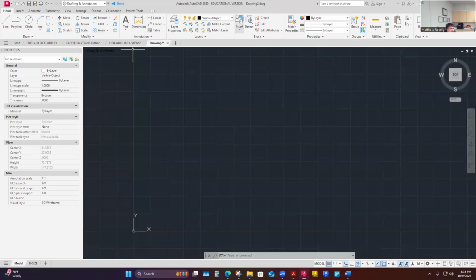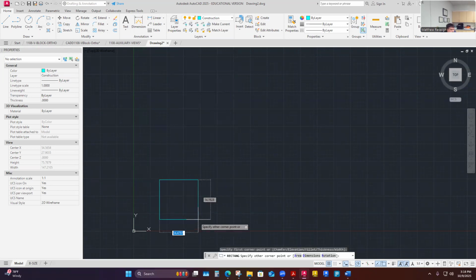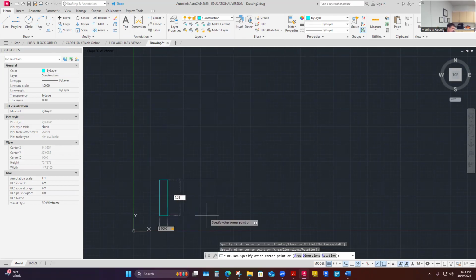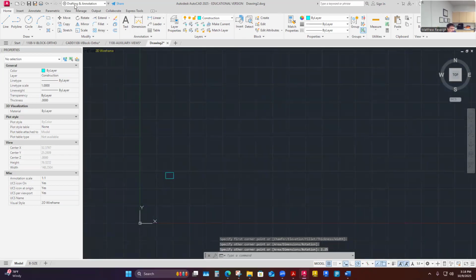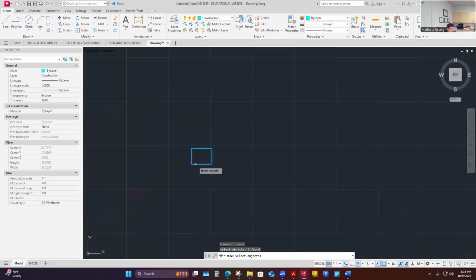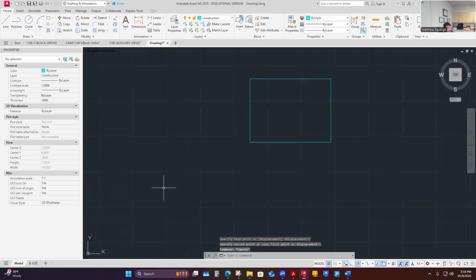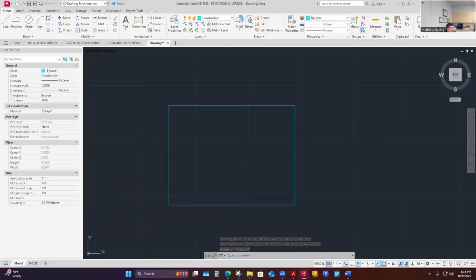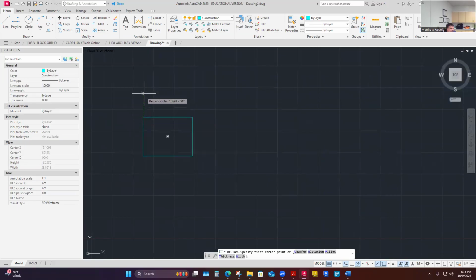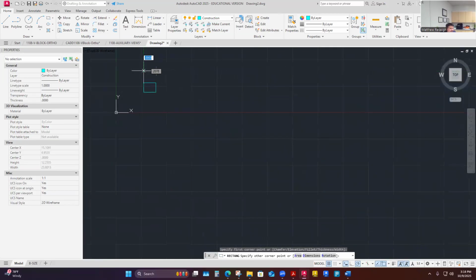So let's do that. Got my construction layer. Let's build this out. I decided it's 3 by 2.25. I'm drawing kind of way up. Maybe I could move this down a little closer to my origin point, but I'm just going to draw it a little closer down here. It's a pretty small object, really. And let's do the top boundary. So I'll drag up here a few inches. Seems like I always need a few inches to dimension.